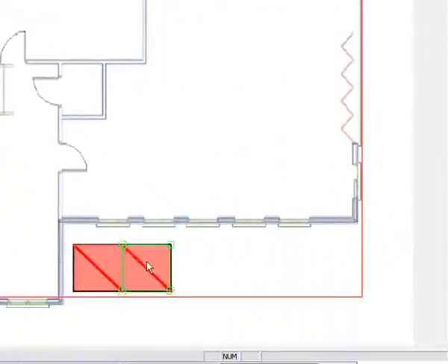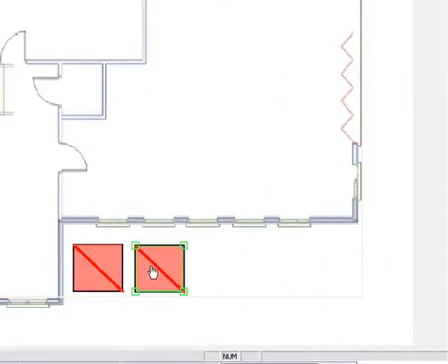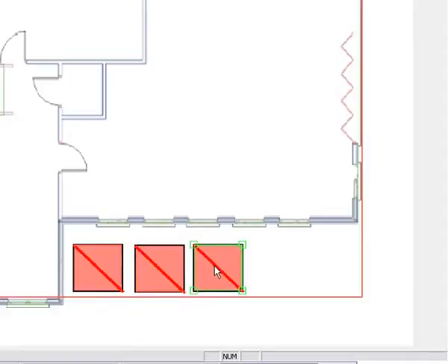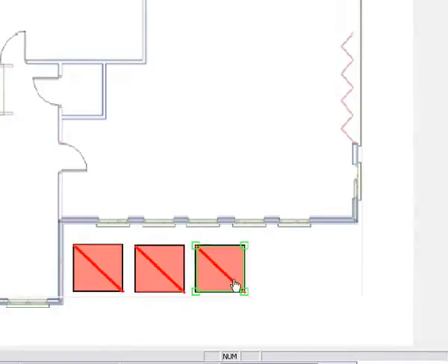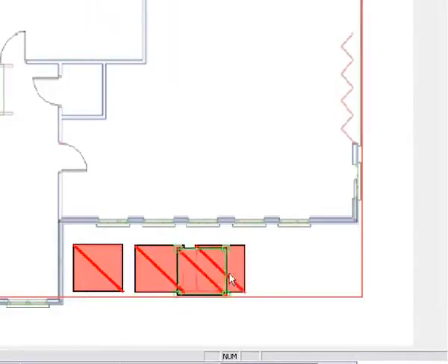We place them aligned and equidistant and we edit them as we did before. We assign them the corresponding destination synoptic. We edit their label and we verify that the layer 3 is marked. We make this in each one of the area objects.